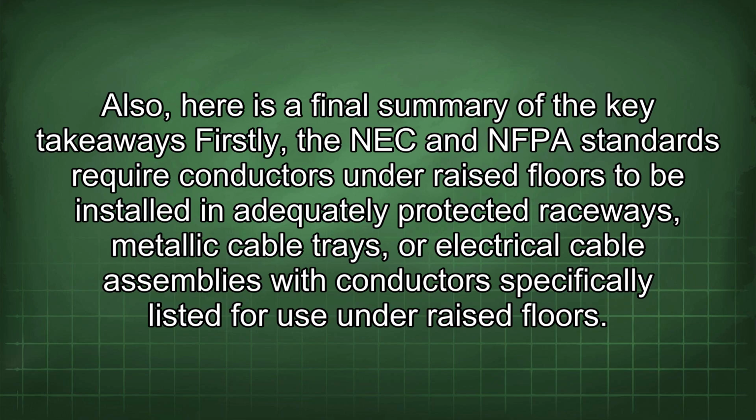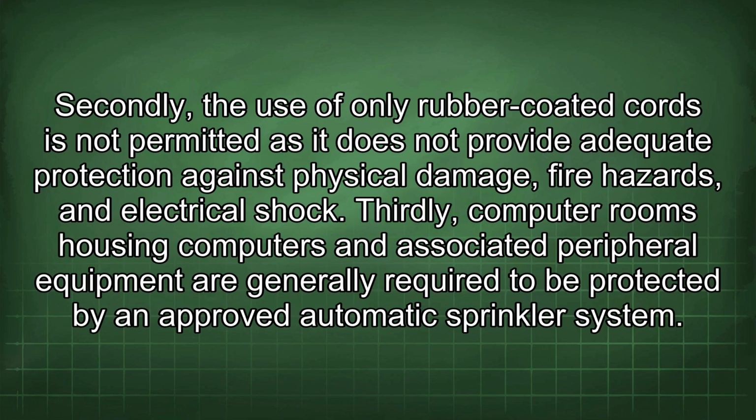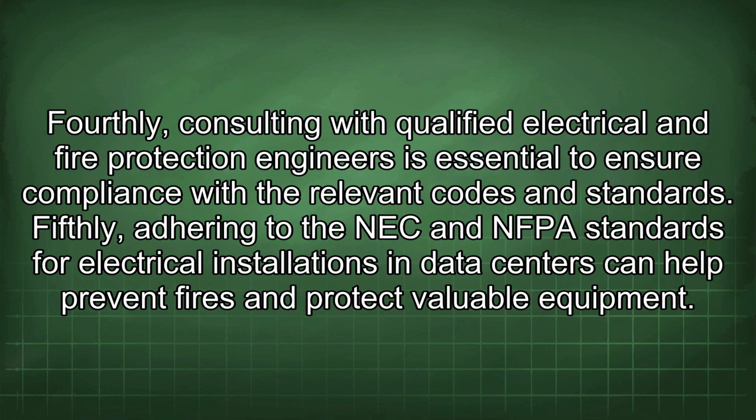Firstly, the NEC and NFPA standards require conductors under raised floors to be installed in adequately protected raceways, metallic cable trays, or electrical cable assemblies with conductors specifically listed for use under raised floors. Secondly, the use of only rubber-coated cords is not permitted as it does not provide adequate protection against physical damage, fire hazards, and electrical shock. Thirdly, computer rooms housing computers and associated peripheral equipment are generally required to be protected by an approved automatic sprinkler system.